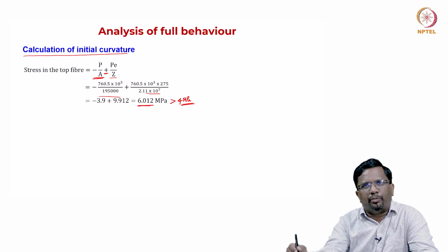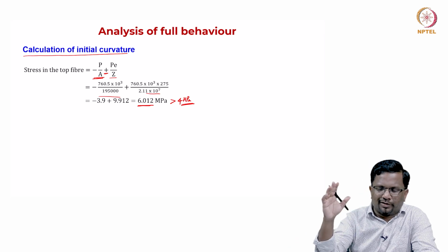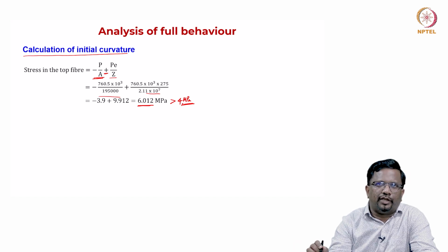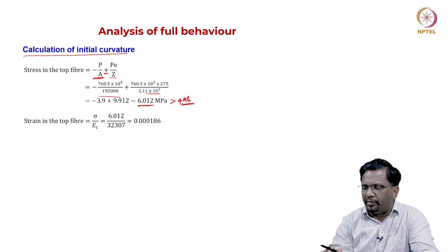You have actually applied too much pre-stressing. Note that when no external loads are acting, this has exceeded 4 megapascal by 2 megapascal. So, you will have a lot of cracking at the top. We have to keep that in mind.